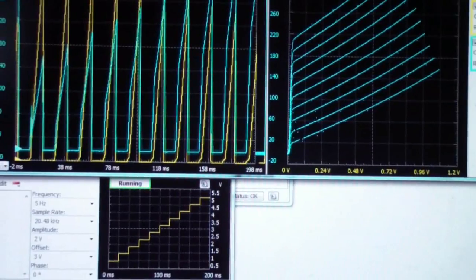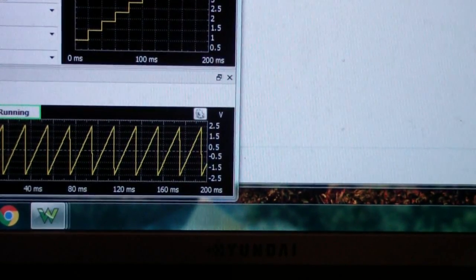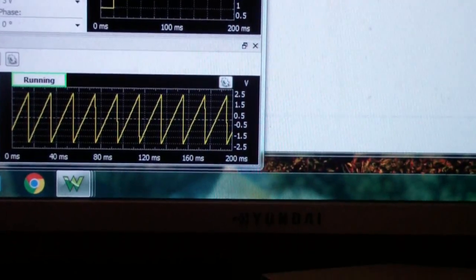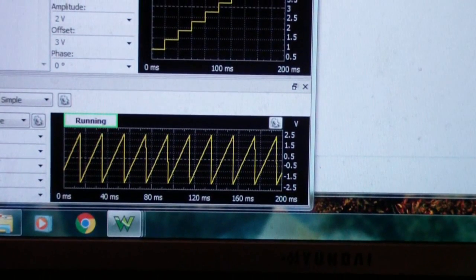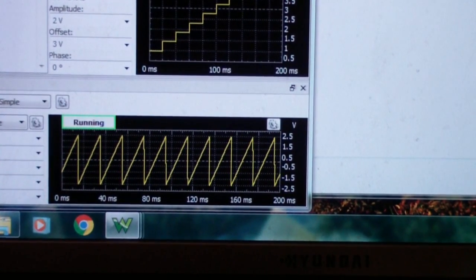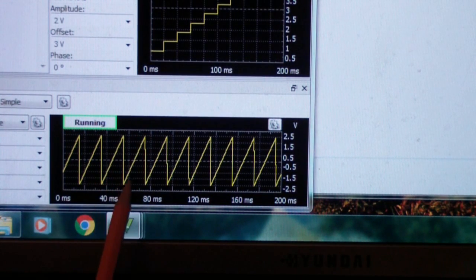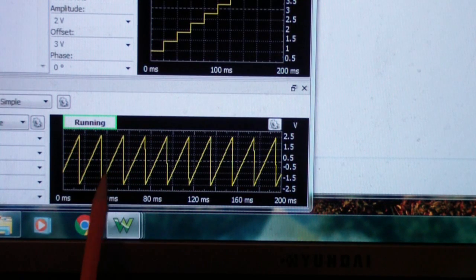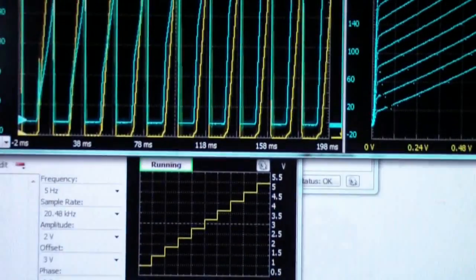The waveform that is sweeping the collector has been changed so that it is much more of a sawtooth and less of a triangle. You may notice that now it rises over actually 90, let's see, I have it set to 98%. So 98% of the time it rises, and then it falls in 2% of the time. That has an impact on the display.